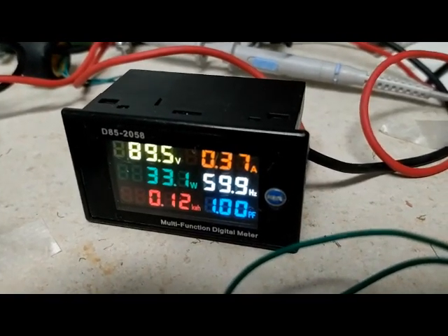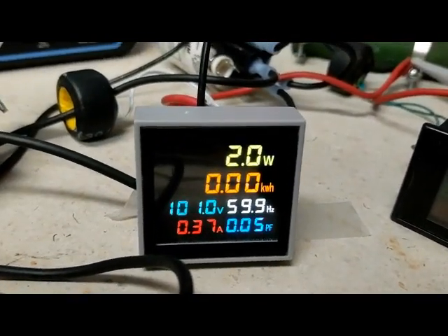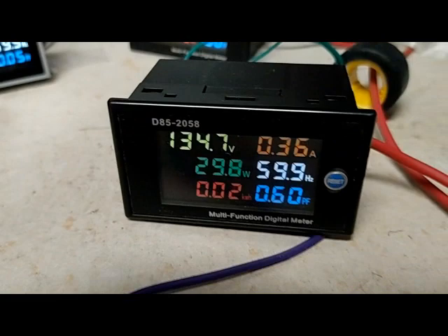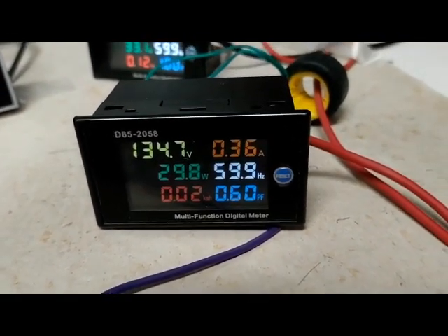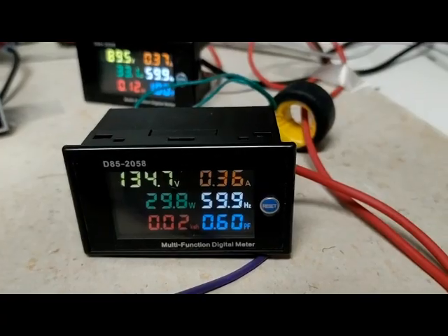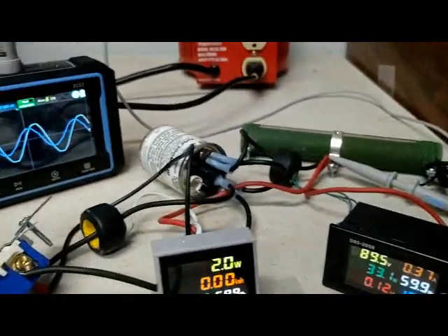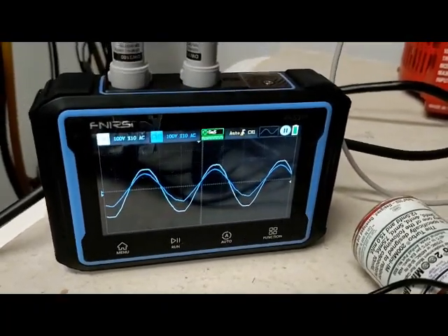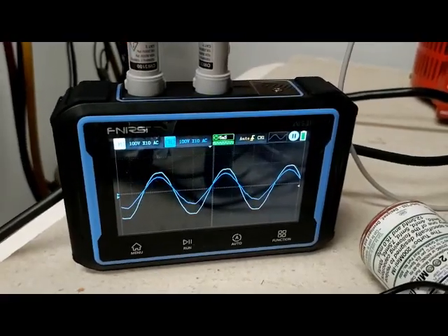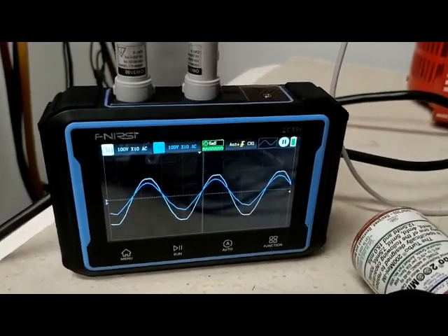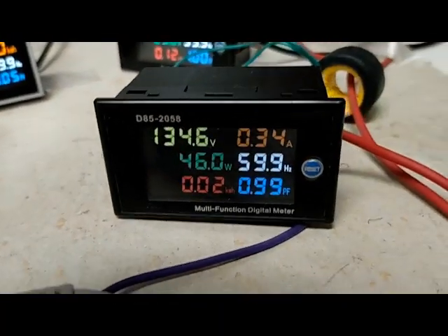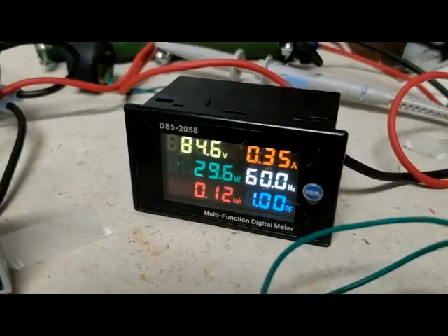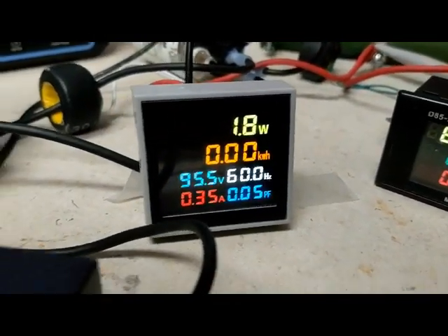The resistor still has a power factor of 1, and the capacitor has a terrible power factor. And the overall power factor of the circuit is 0.6. But magically, if I have both capacitance and inductance, and if they're at the right levels to offset each other, then the current and the voltage are back in phase. My circuit power factor is back to almost 1, even though the power factor for the individual devices has not really changed.